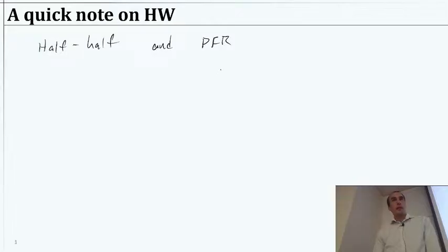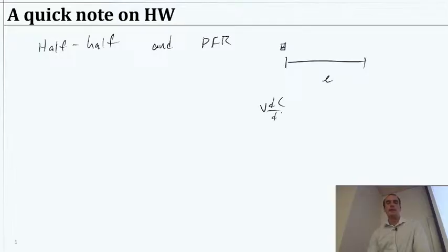Now, a plug flow reactor, first of all, we are going to treat as if we have a batch reactor and it's on some conveyor belt that takes some amount of time to get from the start to the finish, right? So if we think about a plug flow reactor that has some length, we're going to treat some infinitely small little batch reactor there. And I say batch reactor because we did the kinetics of the batch reactor, right? V dC/dt equals plus or minus k C to the nth power. That was our batch reactor starting point, and we'd say that's in some volume.